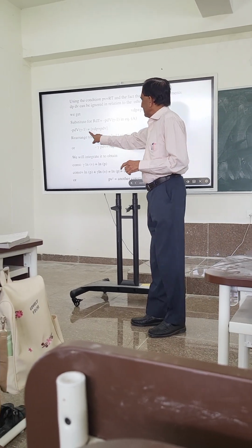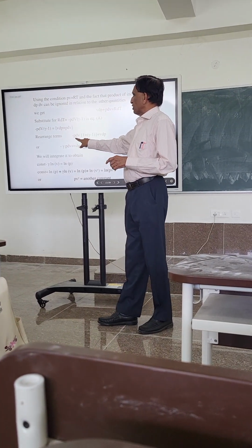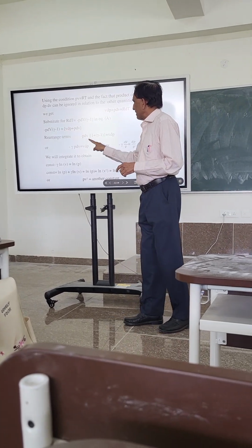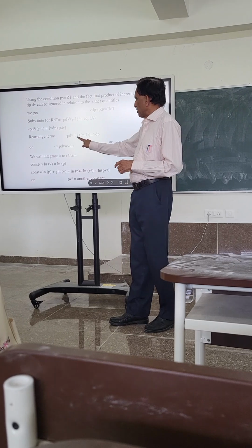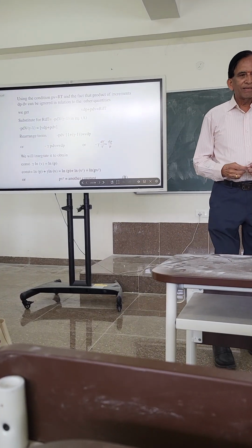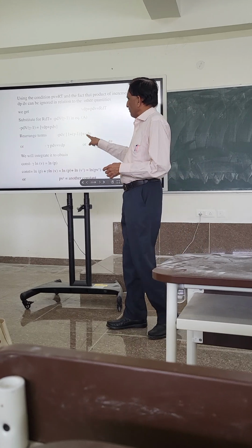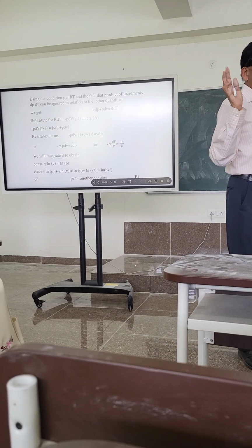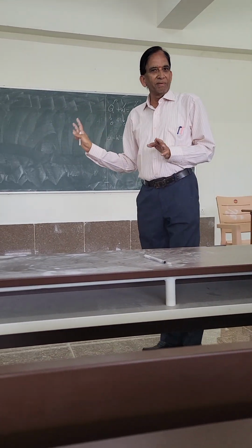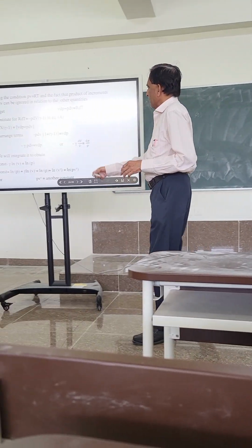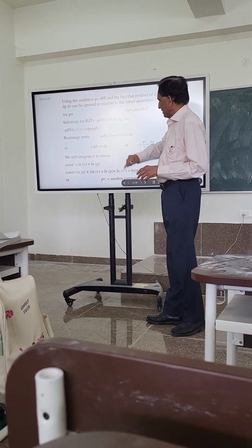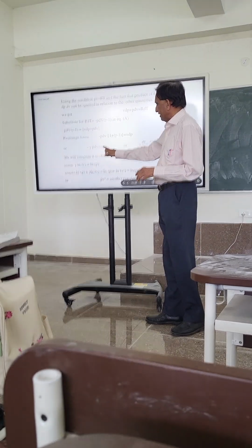Then you again rearrange the terms. So PdV comes out of this one. VdP equals minus PdV times 1 plus gamma minus 1. So this will actually be gamma, because 1 plus gamma minus 1 is nothing but gamma. That should be equal to VdP. Again, remember guys, it is all algebra. There is no thermodynamics here. Correct or not? Okay, let's go to the next step. Now this is nothing but 1, this is nothing but gamma, and the 1 and this one get cancelled. So minus gamma PdV is equal to VdP.